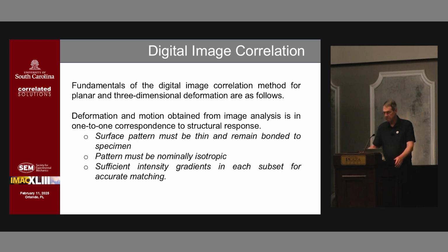First, the pattern must be thin, and it must be bonded throughout the specimen life. Whatever the loading is, you've got to maintain it. The thin is because if you make it too thick, it's going to crack. It's going to behave in manners that are not consistent with what you see in the specimen.